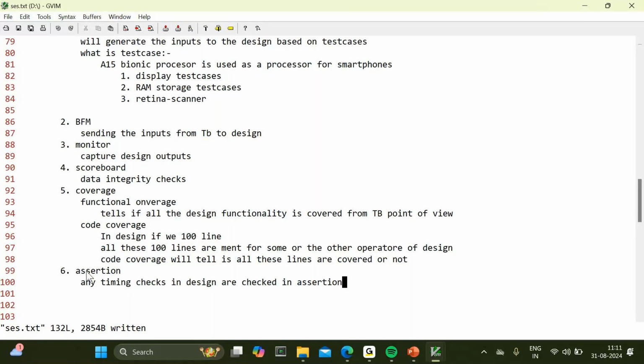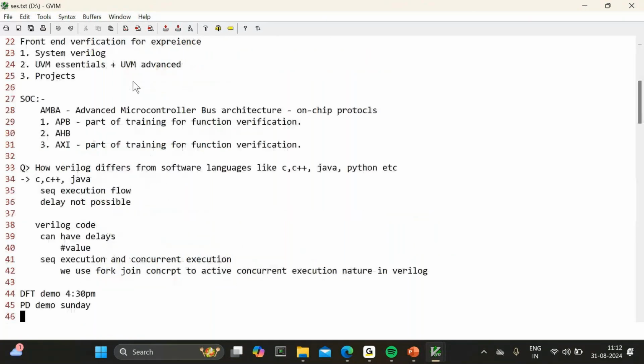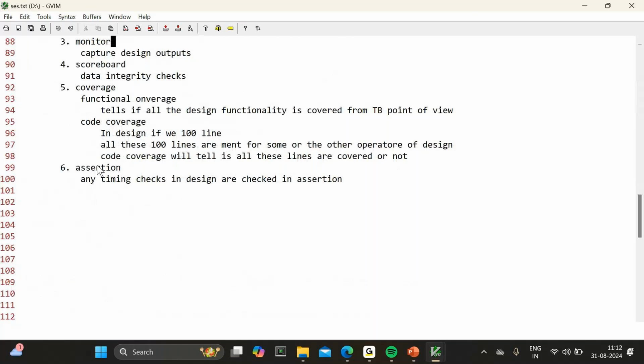One signal might be high in one clock cycle. From the duty, the acknowledgement will come across at some different clock cycle. Those kinds of timing checks we want to implement, we use assertions here. Okay, just in brief I am discussing, because this itself is a separate chapter to be discussed in SystemVerilog and UVM, where we'll be spending around 1 week to understand all these things.